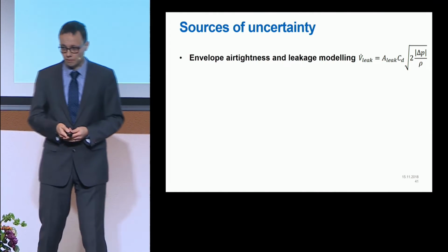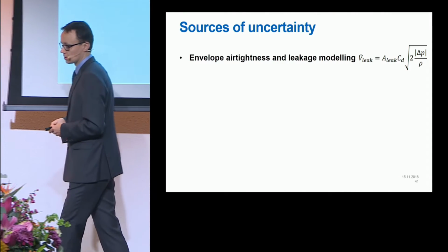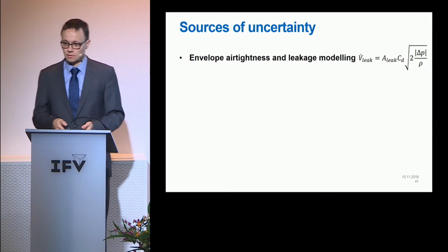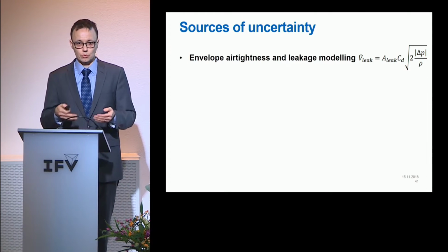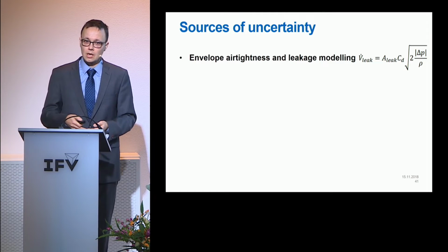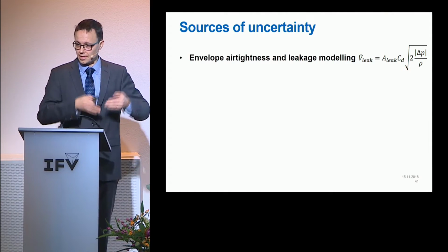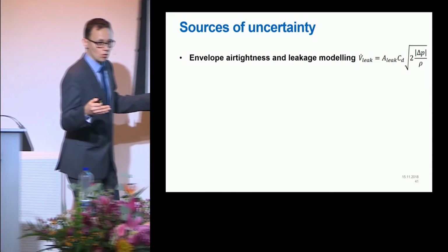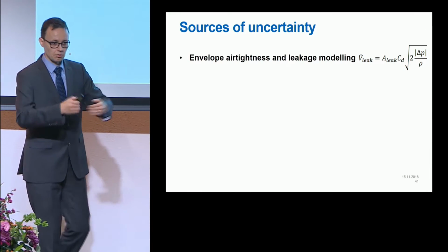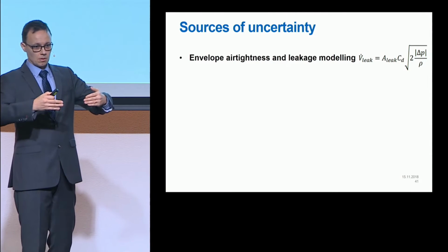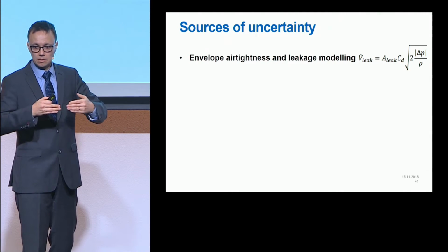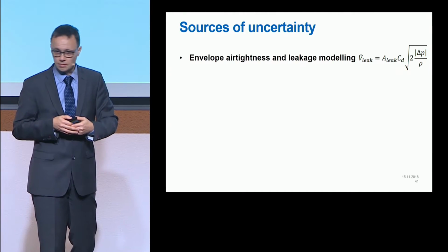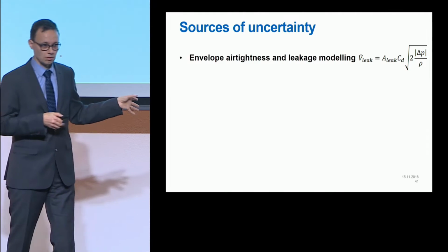When we go from the pressure differences that are typical to energy efficiency measurements, few pascals, few tens of pascals, up to hundreds or even thousands of pascals, it's quite clear that the walls are going to change. Gaps are going to open. It's going to move, bend. All sorts of things happen, and the leakage paths are not the same as in the initial condition.